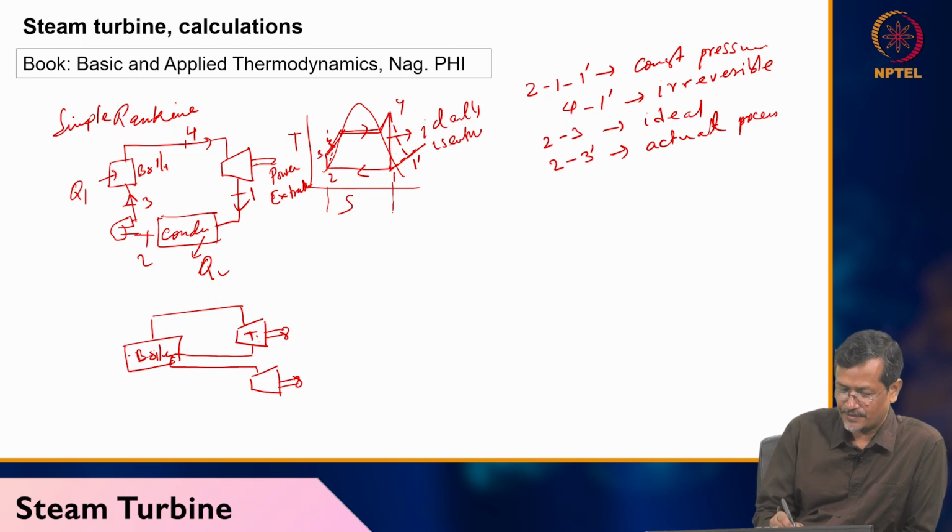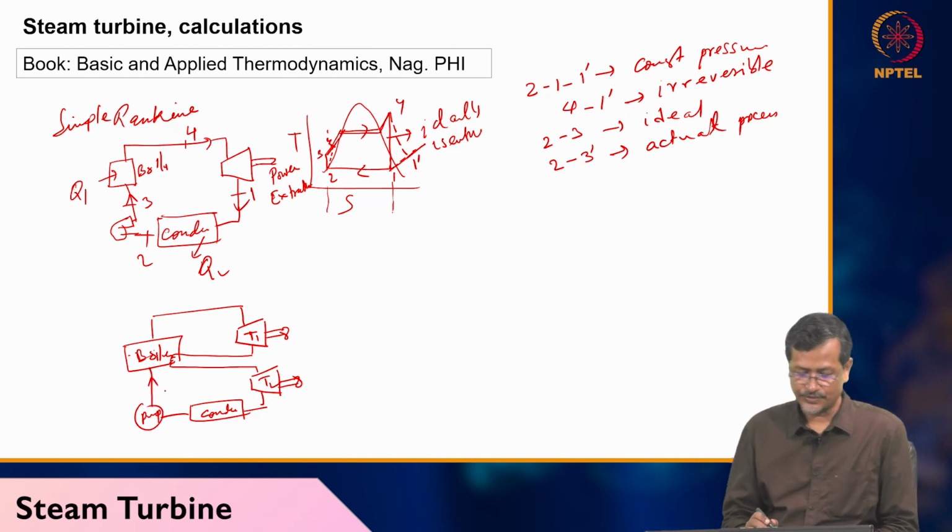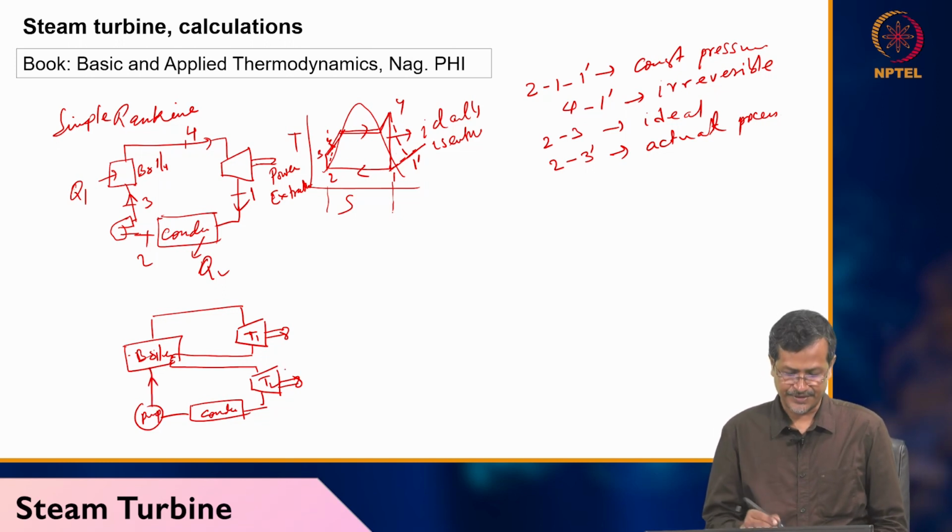So turbine 1, turbine 2, then it is going to your condenser, then condenser to pump, pump to boiler. So you are taking energy 2 times, but you are having the condenser 1 time, meaning you are releasing less heat actually. So you are improving the performance of your system. Maybe 2-3 stages are possible.